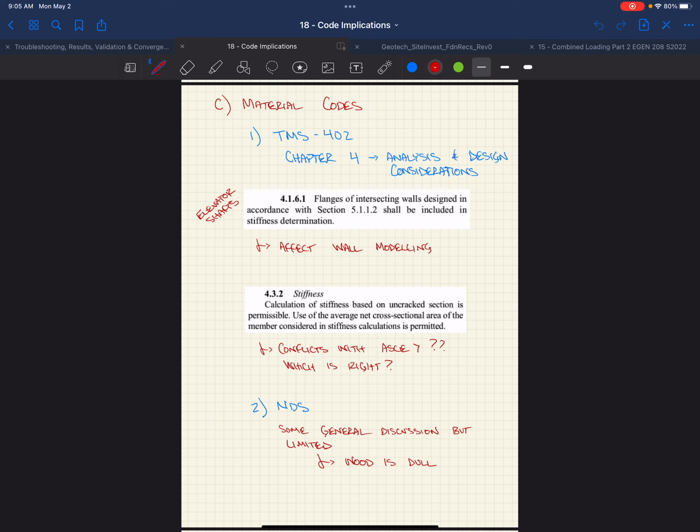When it was built, you got a few people out on that landing, started jumping, and the thing started resonating. So now, if you go out there at the landing level, there is a support that hangs it off of the floor level above, because the natural frequency was too low and you could excite it. You don't want that in the real world.